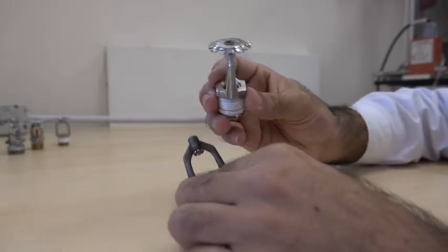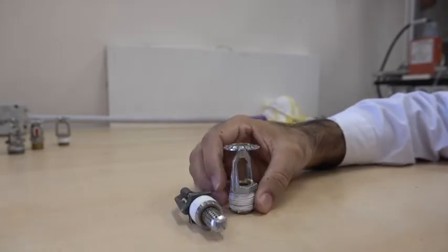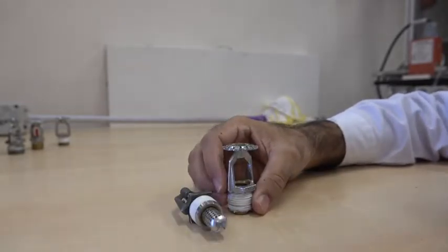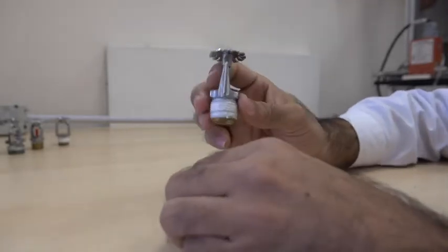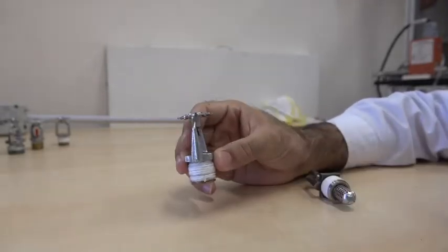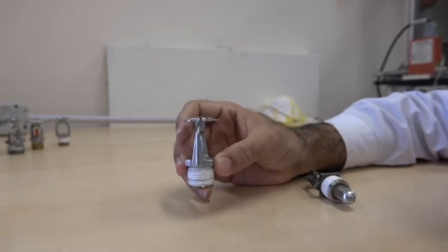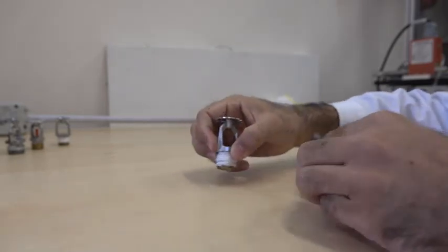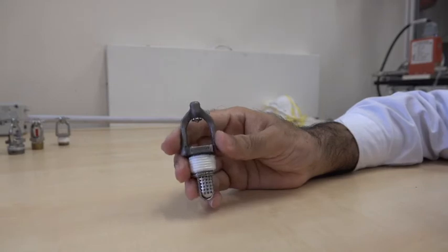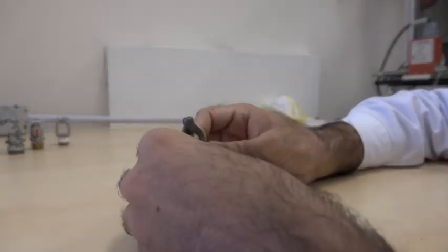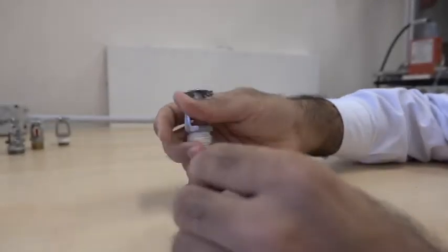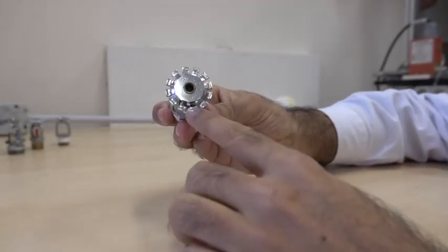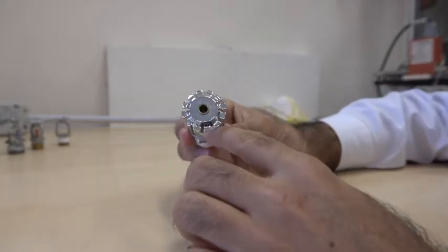These are the standard sprinklers which are used in your office rooms and buildings. You will find these sprinklers, but they are basically used for controlling the fire, not to suppress it. But the water mist nozzle is designed to suppress the fire. You can see the difference here. Mainly, you can see the orifice size is quite small in comparison to standard sprinklers, which makes a huge difference.